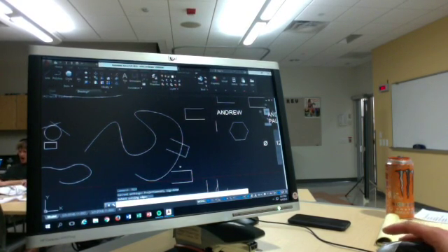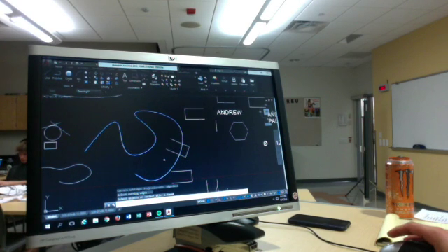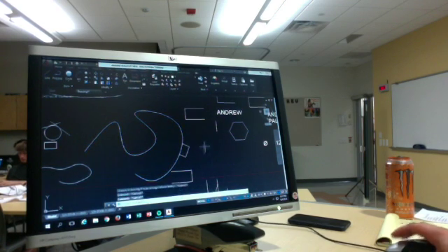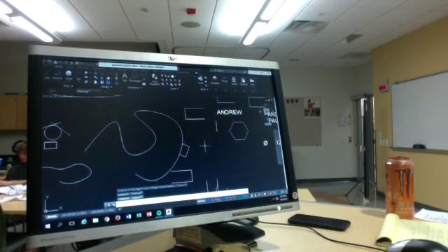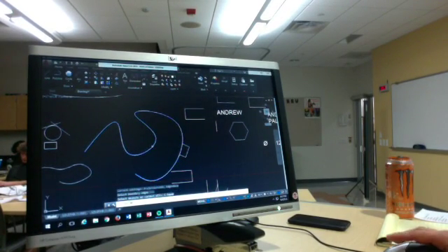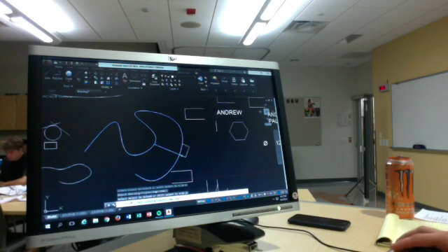First, you select the object. The first thing that you choose is the object that you use to slice. So I'm going to choose that. You hit enter. Then we choose the objects to slice, which is these two objects. Same thing with extend. So type in extend or choose it from your ribbon up at the top. We are going to be extending to this item. Hit enter, and then we choose the items to extend.